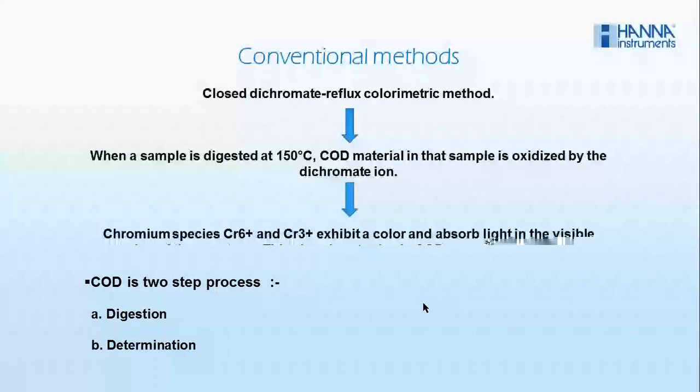Now, the advantages and disadvantages of these methods. The advantage of the closed reflux method is that it is very quick and reliable as compared to the open reflux method. Closed reflux vials are pre-dosed by the manufacturer, whereas in the open reflux method you have to prepare the reagents and do the standardization. So it is a very time-consuming method for the analyst.